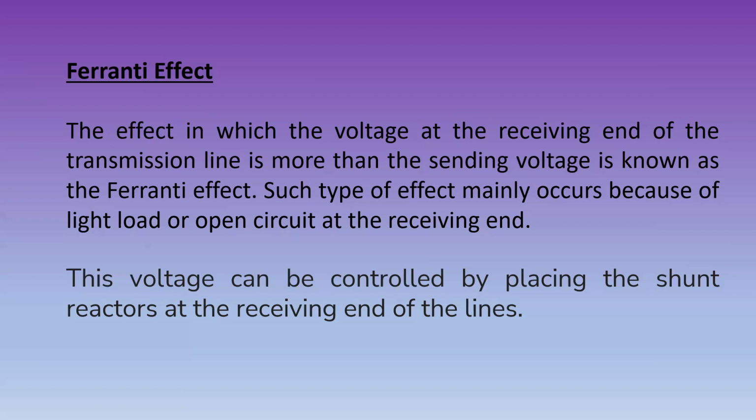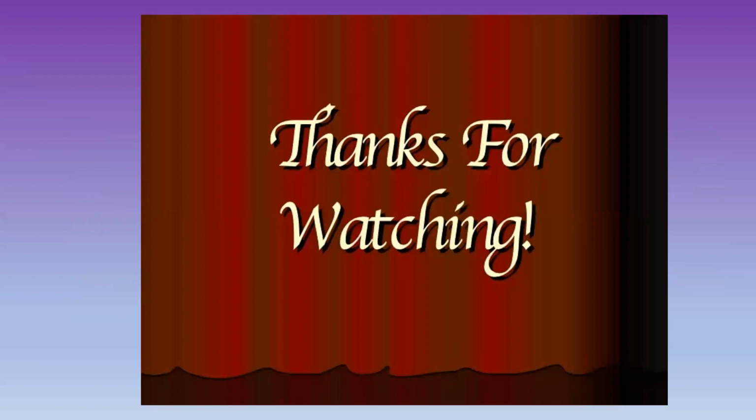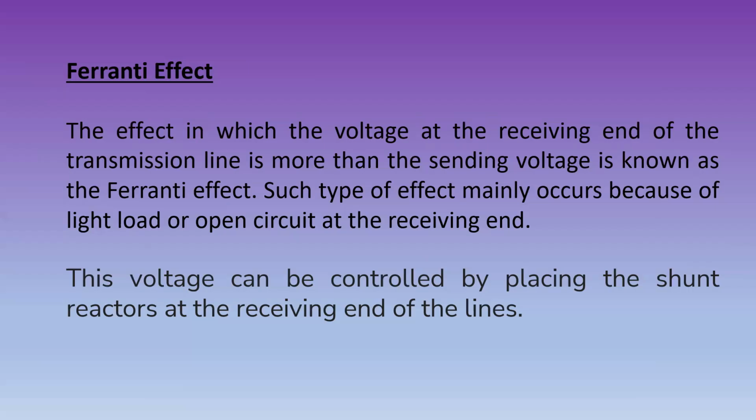At last, we are going to see about transposition in the transmission line. So what is transposition in the transmission line? Transmission lines are transposed to prevent interference with neighboring telephone lines, to balance the voltage drop, and to reduce the unbalance of current and voltage.